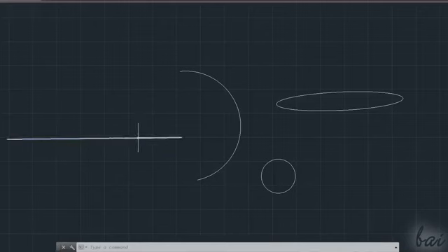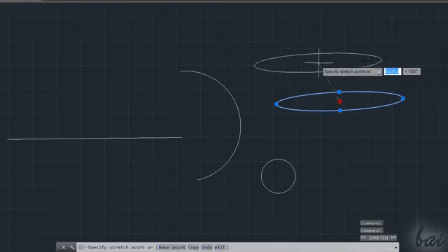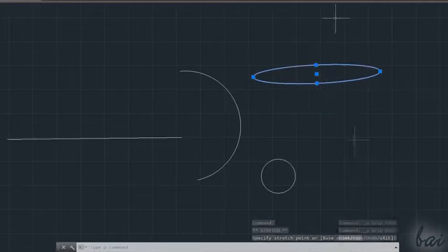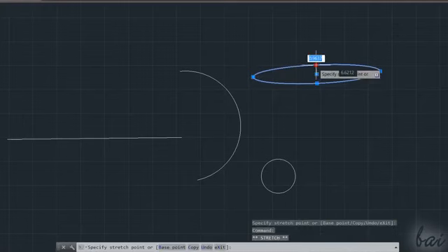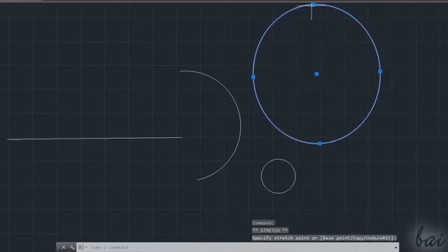Let's see how to edit your object. When you select lines, circles, ellipses, and arcs, you will get some blue nodes on their center and path. If you click on the central node and drag, you will move the whole object where you like. Whereas you can use the other nodes to change the object shape. Hover on these to get quick information on the object angles and length, and click and drag one to edit the object shape. Click again to fix the modification.